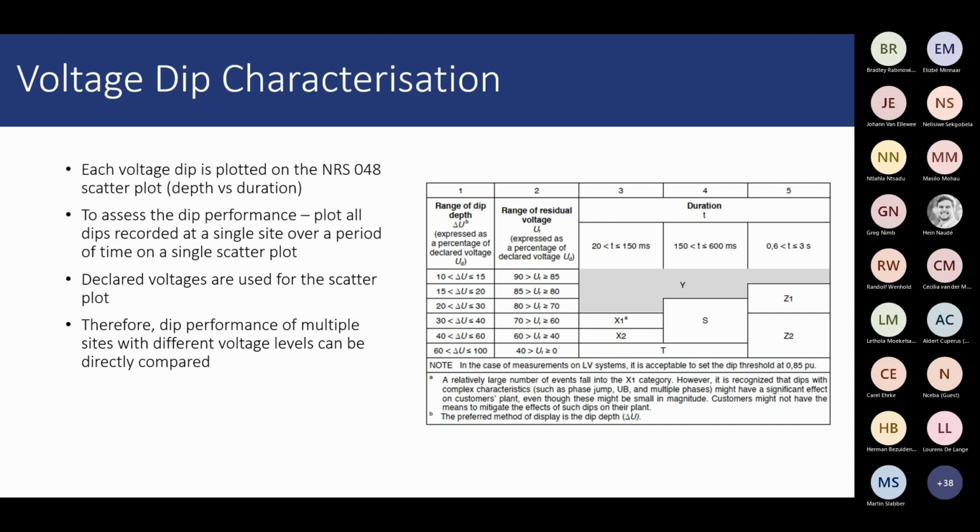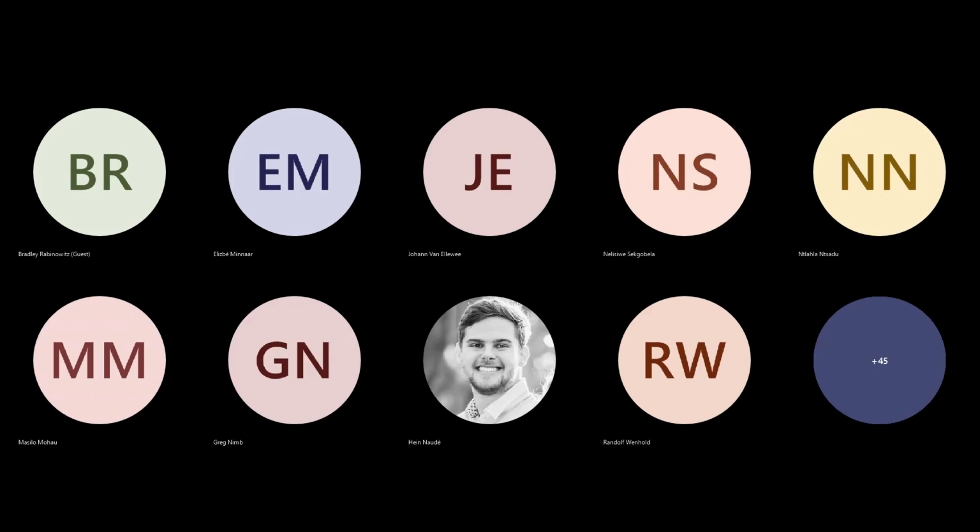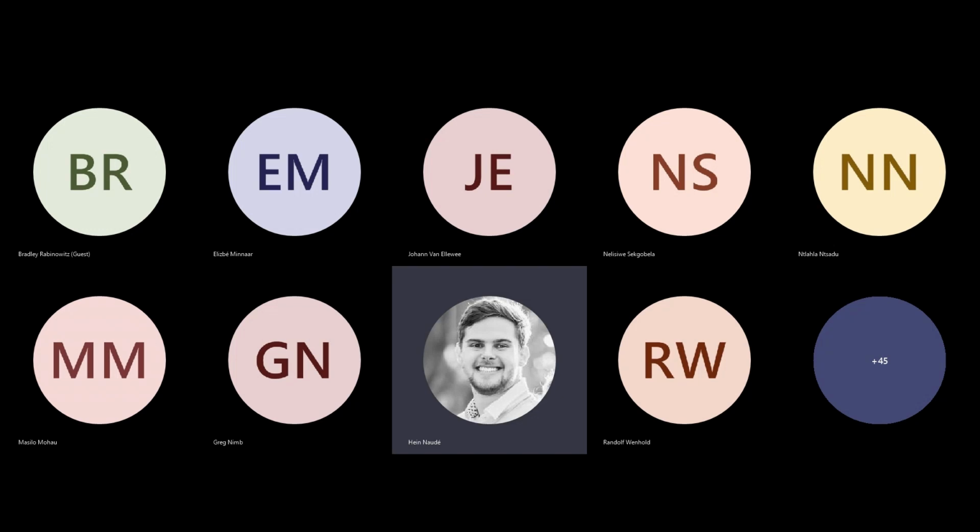The same with unbalance. If we are currently measuring in real time, you have a value of say 0.5%. All we would do is set a threshold of maybe 0.3%, just so that it can trigger, just to test if the alarms go through. So we usually test it without an Omicron, but that's now on the waveforms and not on voltage dips. So yeah, I think that was just my observation. Yeah, Brandon, that is 100% correct.